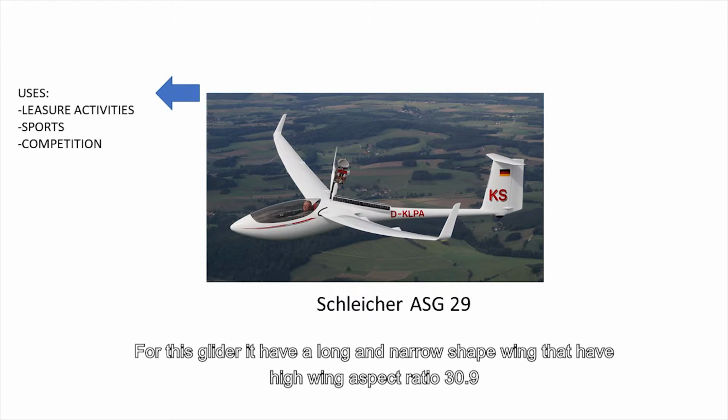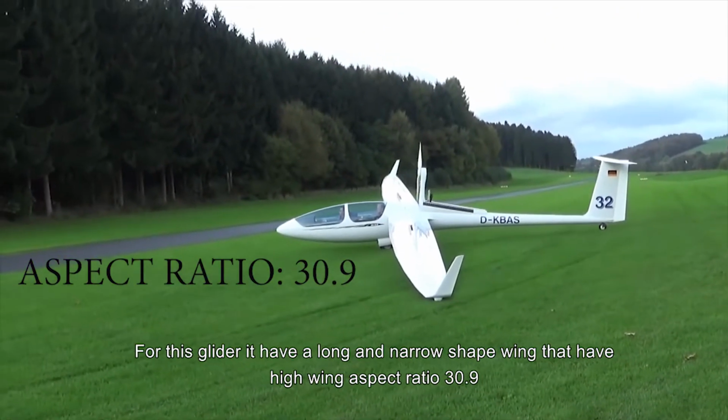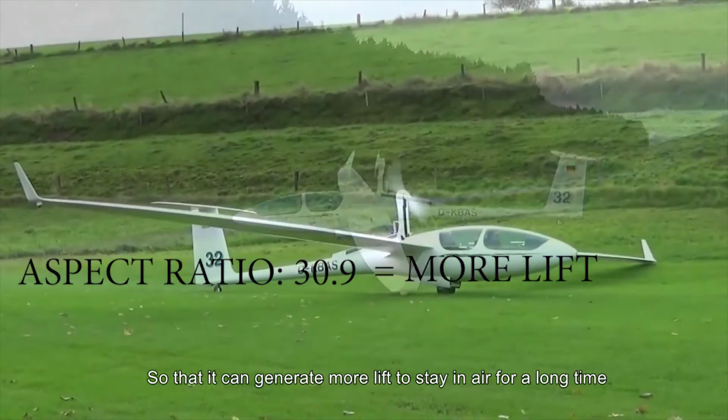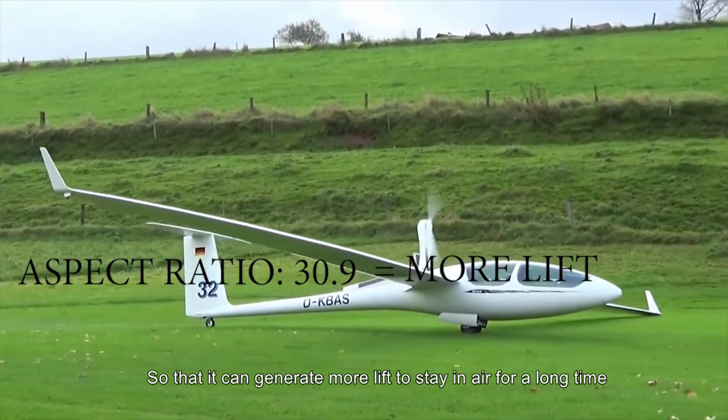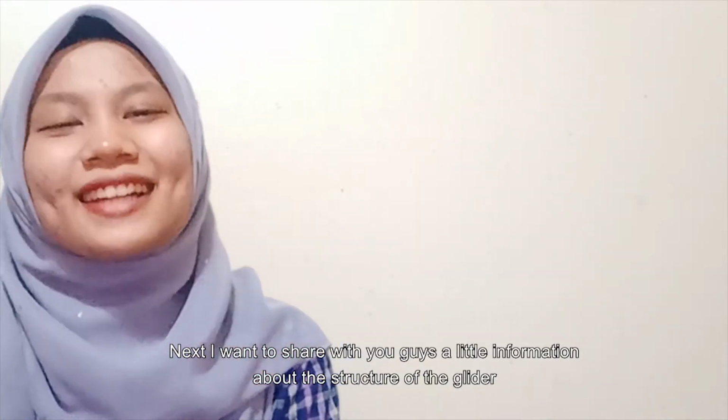This glider has a long and narrow wing shape, thus it has a high aspect ratio, which is 30.9, to enable it to generate more lift so that it can stay in the air for a long time. Next, I want to share a little bit of information about the structure of the glider.